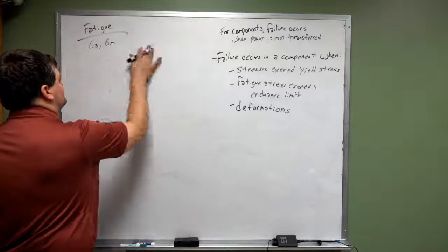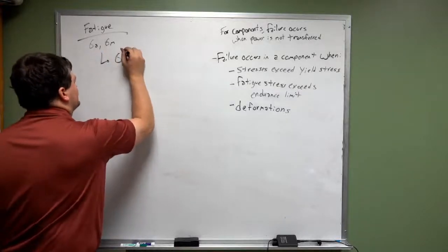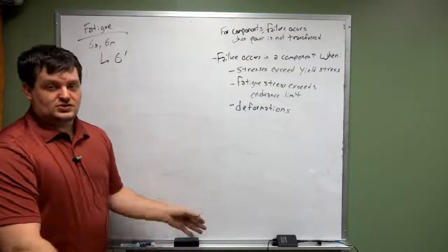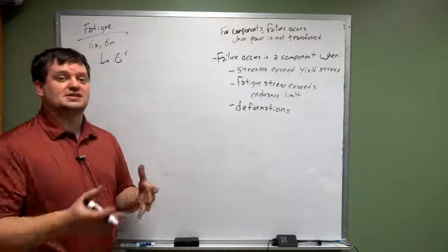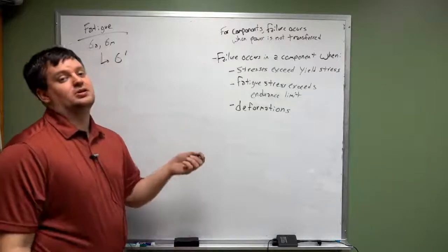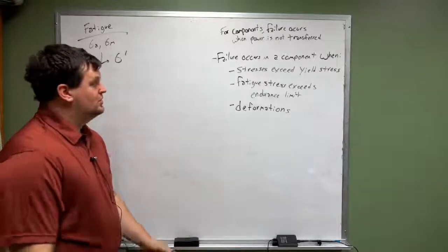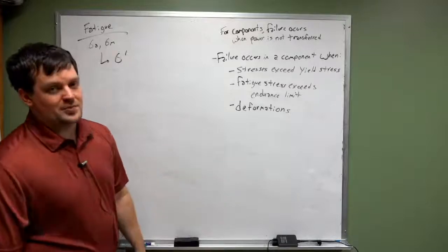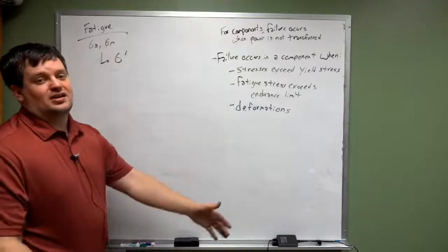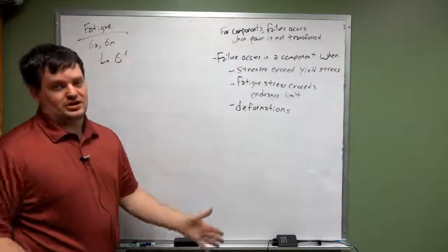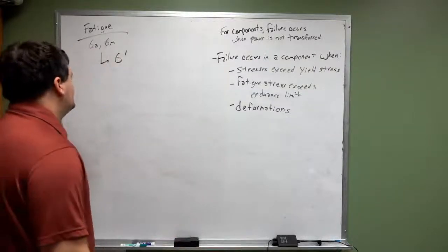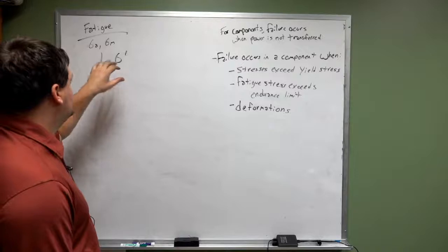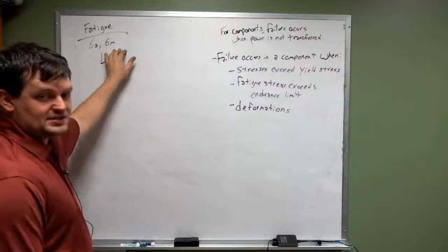Okay? Both of these are calculated by figuring out what your von Mises stresses are at certain locations. And it's how your von Mises stresses at a certain point on your component shift from minimum to maximum. That determines your sigma A and sigma M. You may have a negative value, you may have a positive value on one side. Your sigma A may be 180-degree reversal of loading. Okay? But again, it comes down to determining your von Mises stress for your component. Okay? Figuring out then what your sigma A and sigma M are.